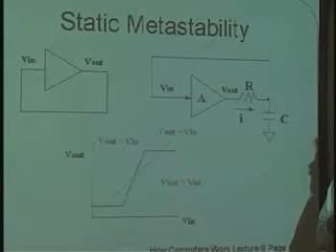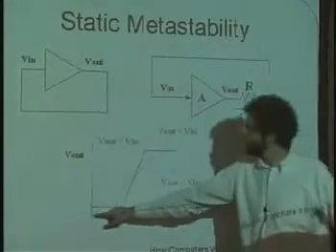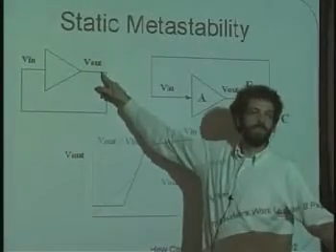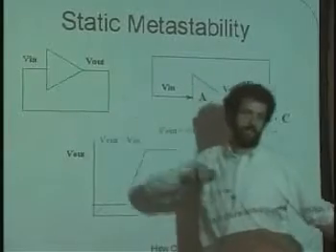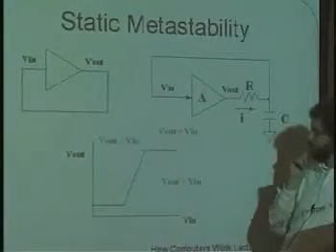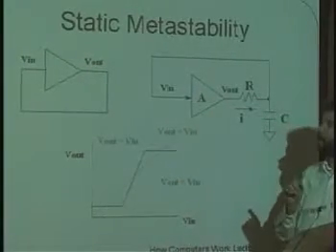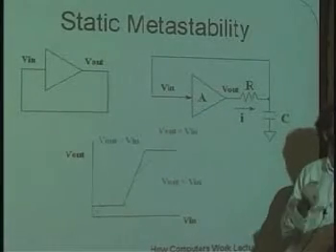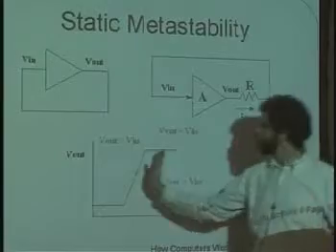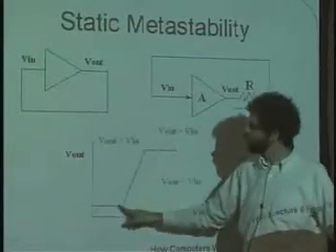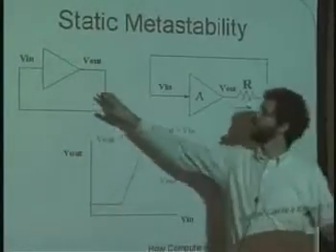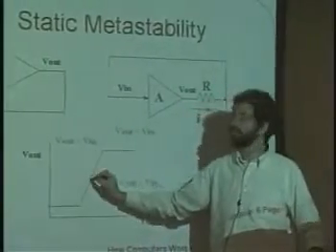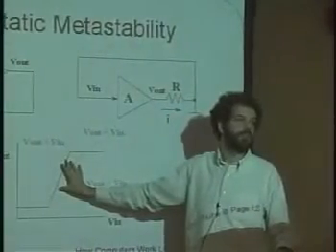And what the gain means is that instead of this straight line over here, which would be V out equals V in, in other words, the output of a gate like this is equal to the input of the gate, what the circuit does is it says, look, I want to make sure that in order to hold on to this output, I have some amplification of the signal. And so the slope of the line, this dark line here, which is the transfer curve of a circuit like this, in fact has a slope greater than 1. The output is an amplified version of the input.